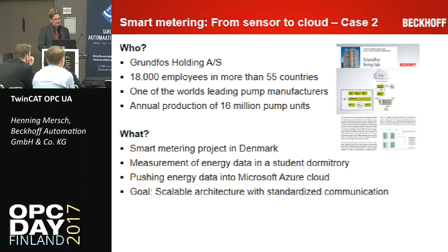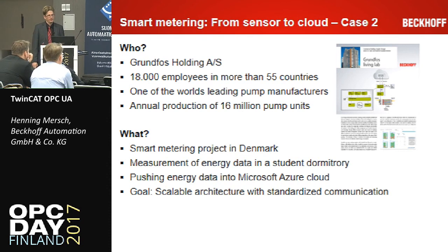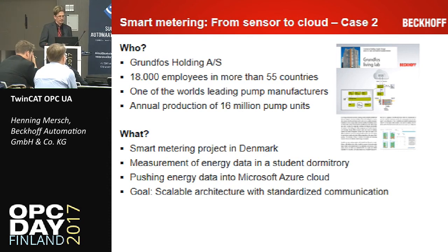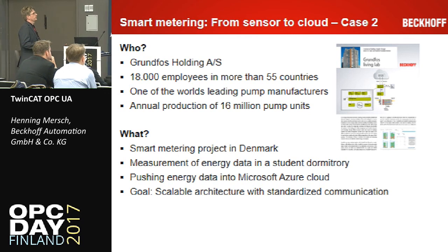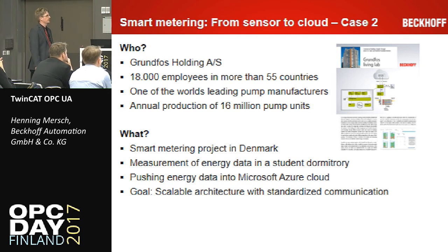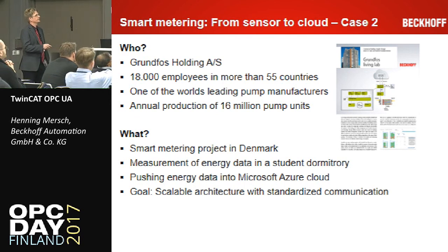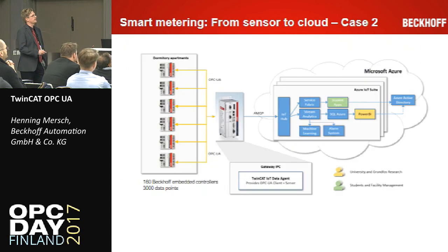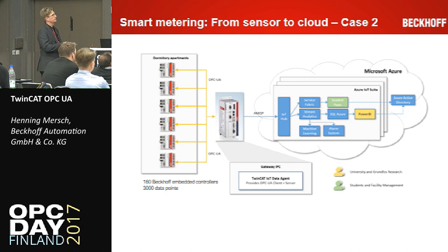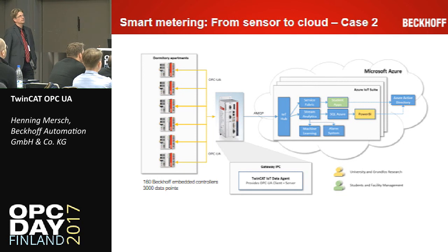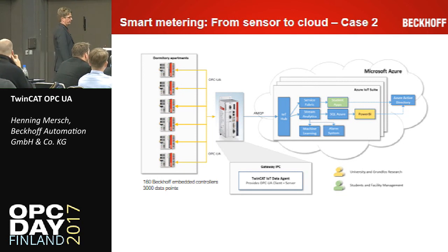And the last success story is about Grundfos. They had an interesting project within a student house. They have 160 Beckhoff embedded controllers placed with 3,000 data points. They're aggregating that to one big IPC, and this is internally done by OPC UA. And externally, they are pumping it up into the IoT hub using AMQP. So this PC is more or less acting as a gateway, from the OPC UA world to the cloud world.